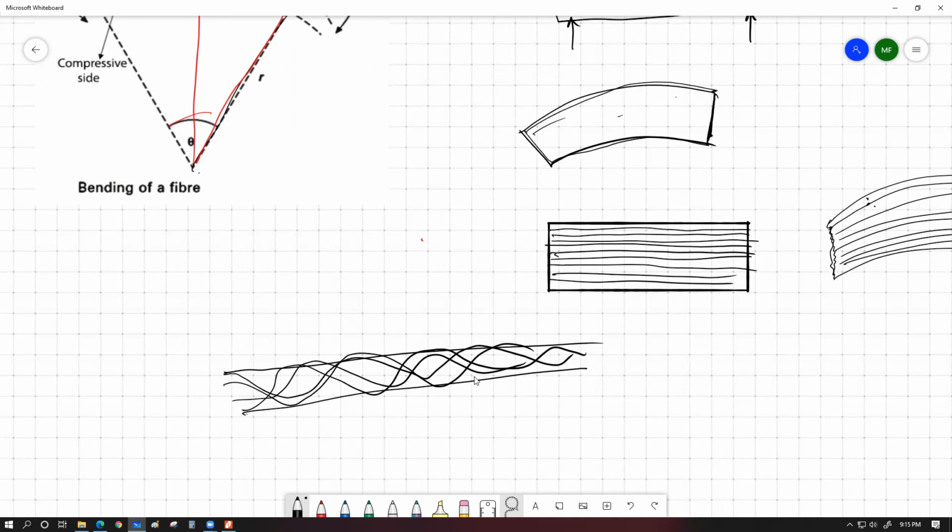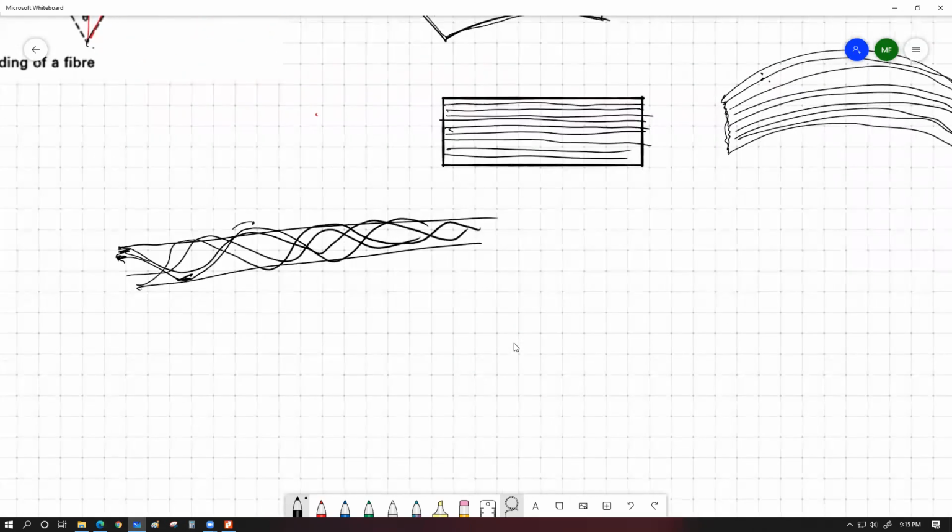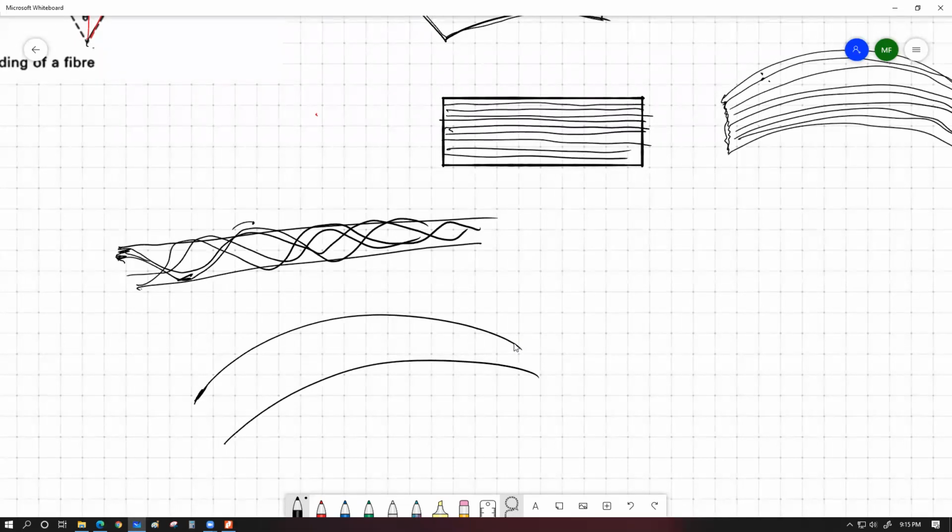Notice one thing: one single wire is on this side and also on this side, also on this side. So whenever this cable undergoes deformation, let's say I bend this cable, one wire is going to experience tensile load on this part and compressive load on this part, but it's not actually going to have to undergo this compression and extension, because it can deliver the extra length needed on the outer side, and it can take less length over here on the inside. So it can simply give out the length in the necessary places, ultimately keeping the average length the same over the whole cable.